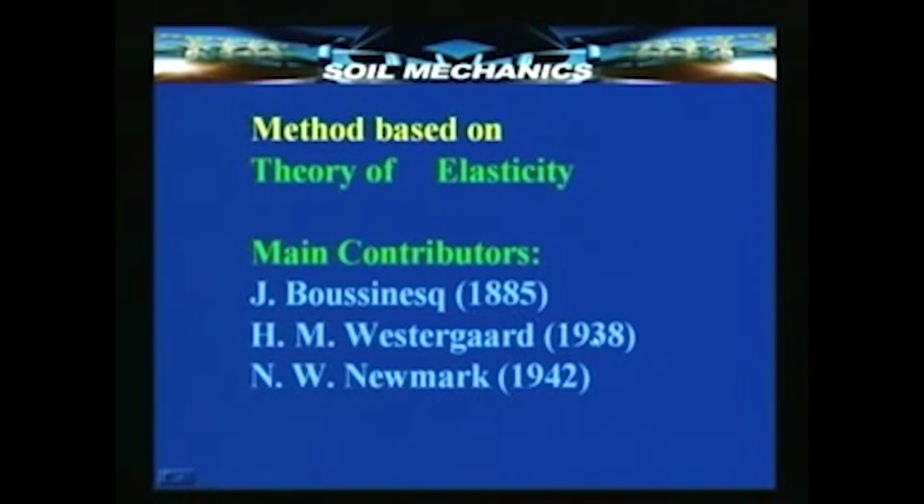They have all contributed at certain intervals of time to the computation of stress distribution below a foundation using theory of elasticity. There are many others who have contributed subsequently, but some of the major, conceptually different contributions have come from Boussinesq, Westergaard and Newmark.